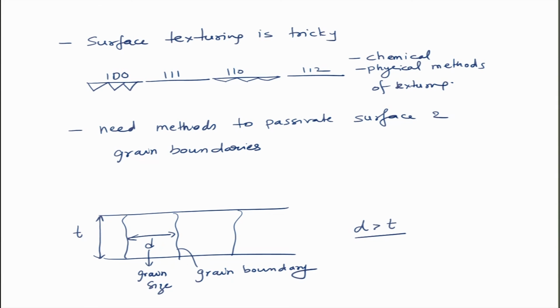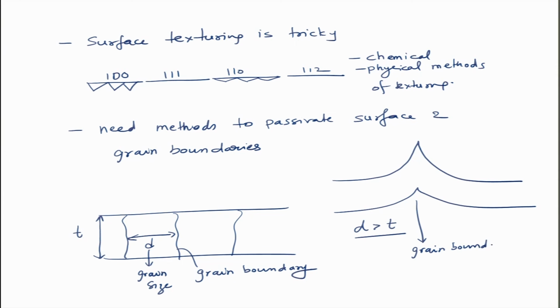Another thing that you often come across is, since you have a grain boundary, the energy at the grain boundary leads to formation of an energy barrier. So, this is the grain boundary. It forms an energy barrier for carriers, and because it is an internal surface with dangling bonds, the carriers also get trapped.